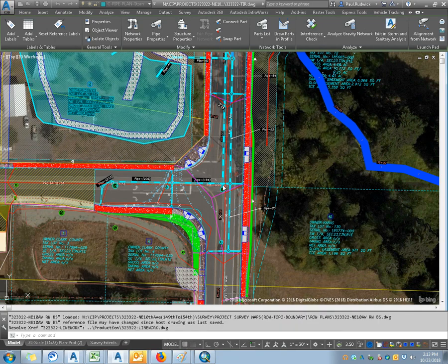However, in Civil 3D, there is no way to do that effectively. So we're doing some more workarounds to make it look right in the drawing. I have multiple pipe networks on top of each other that aren't actually connected, which you would think doesn't really matter. Well, it does matter when you're trying to import it into SSA. When this opens up, I'll show you here.